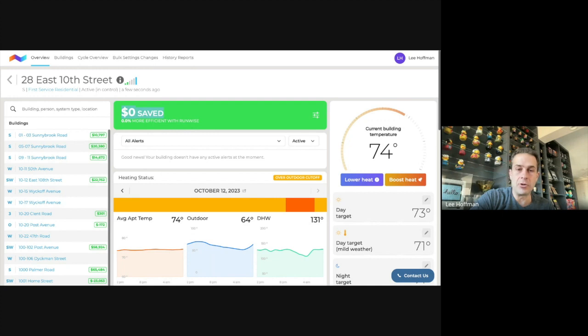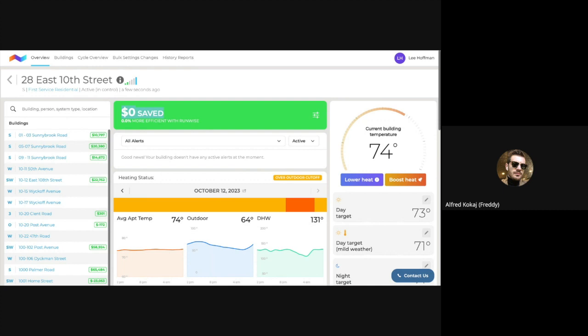Above 1 gallon per unit, it's likely there's some kind of leak going on. So if I have a building with 100 units, 100-gallon water loss, per what time period is it measured? Per day. So 100-gallon water loss per day is considered within the normal.